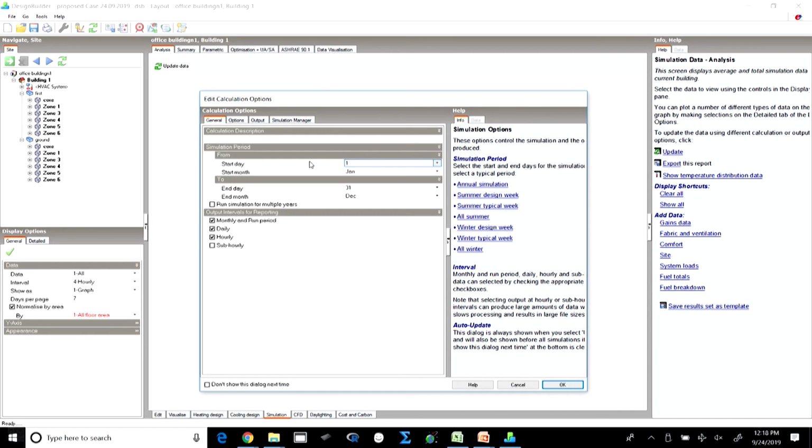For example, the U value of wall can be compromised with because the U value of the roof has been reduced substantially, even beyond the ECBC prescription. So, whether those changes in parameters can be brought in, that is what the whole building simulation facilitates us.